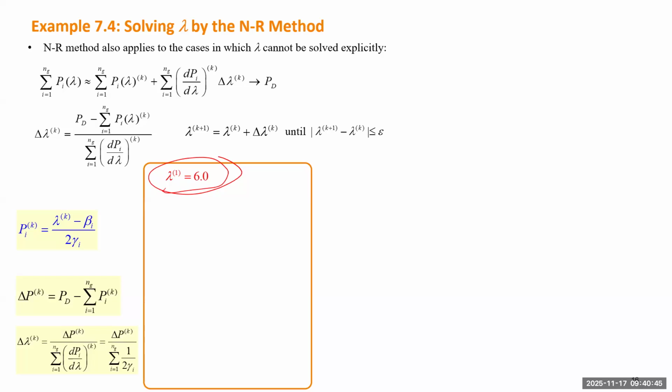So in this approach, I have this initial price, and I just plug it into this formula. I assume this is our formula from step number 2, right? Instead of giving it the accurate price, I just gave it an arbitrary value. So it will tell me some output. Then I plug this output into the power balance equation. So definitely the equation will not be 0. There will be some gap. Then using the gap, I do iterations based on the Newton-Raphson approach. It will tell me something I need to update for the price. Then I go to the second iteration.